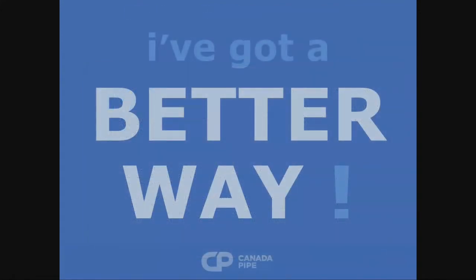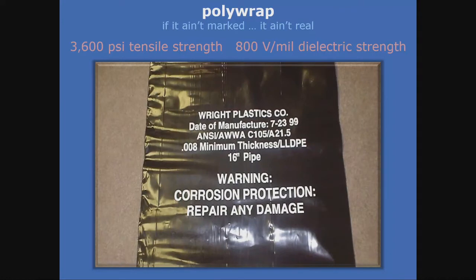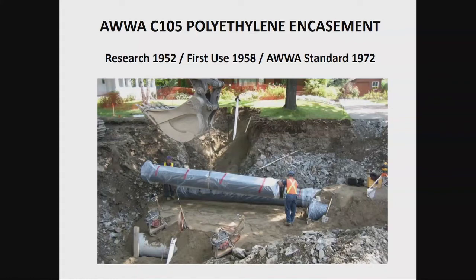So I've got a better way. And my better way is polyethylene encasement. And it will take the pipe out of the equation. So just some background information, it was researched in '52. It was first used in 1958, and then it became a standard for AWWA in the early '70s.